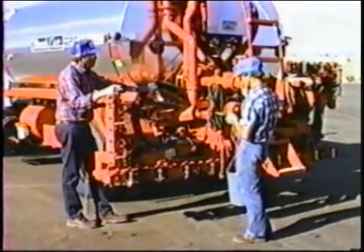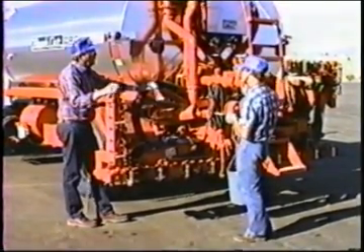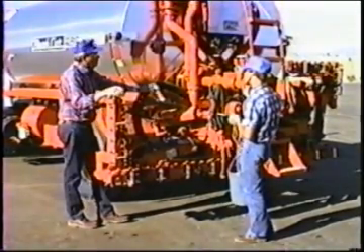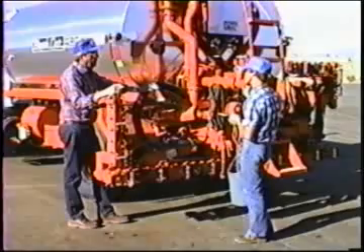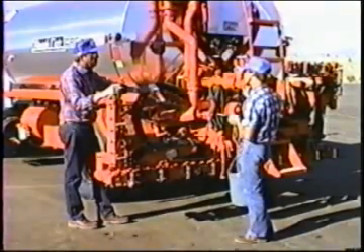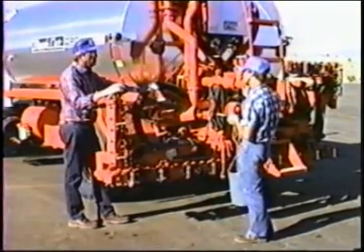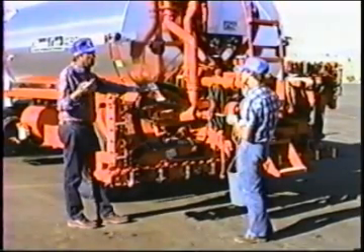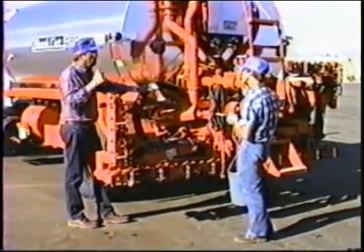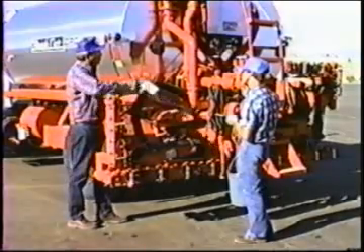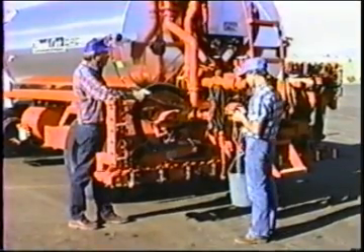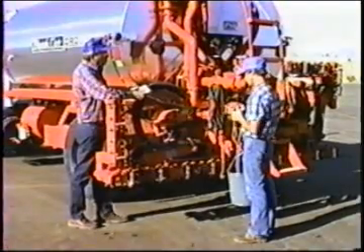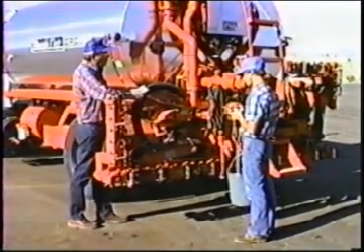Okay, if we're manually spreading and we need to change the bar width, of course, if we narrow the bar down, it's going to try to increase the pressure, because we've cut down the number of holes that the material can get out, so we've increased the resistance. When we increase the resistance, the pressure goes up. So if we're going along here spreading it, let's say we hold it at 400 feet per minute, our pump is turning 100 and...